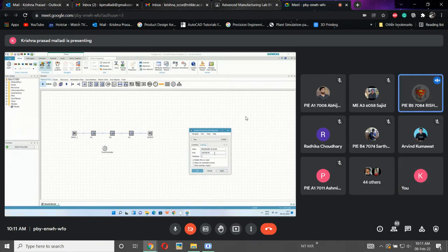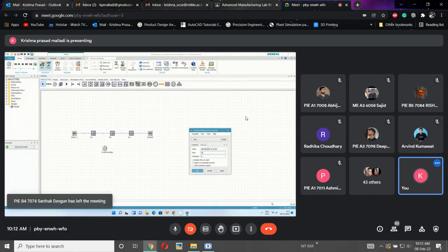Sir, can you explain once more, please? Okay, fine. If I want to run the simulation with respect to seconds, say for 45 seconds, then I need to give 45 and click apply. What will happen? See here, 0, 45. So 45 seconds will be considered. Whatever the figure you want, if you write 10 and click apply, it will be denoted as seconds only. If you give 75 and apply, what will happen? 1 minute and 15 seconds, it will be considered like this.